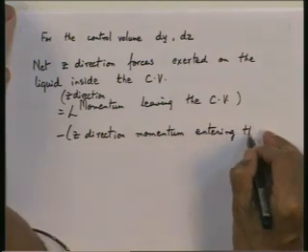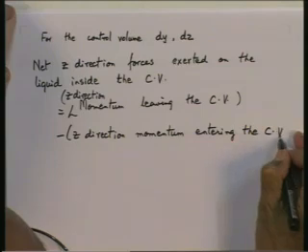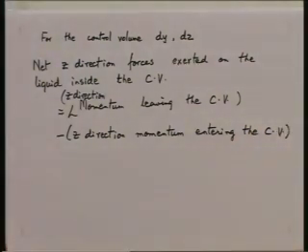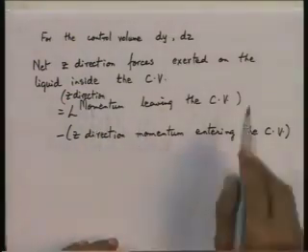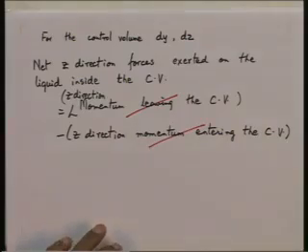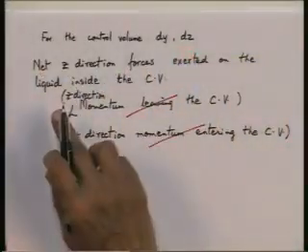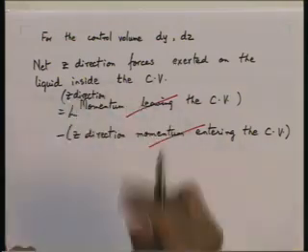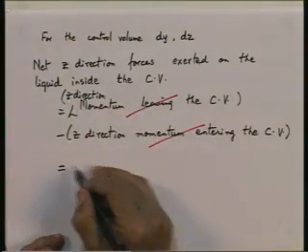That is Newton's second law as applied to a control volume. In this particular case, the difference between the terms on the right hand side is negligible, momentum effects are negligible. Therefore, net z direction forces exerted on the liquid inside the control volume is equal to 0.